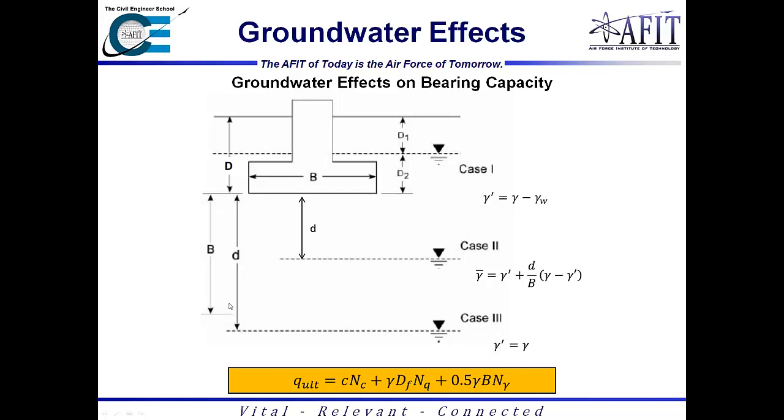So just something to keep in mind if you are calculating the ultimate bearing capacity and you see water table thrown in there, you're probably going to have to consider one of these. Hopefully it's case 3 or potentially case 1. Case 2 isn't that much harder, it's just the equation's a little bit more cumbersome.